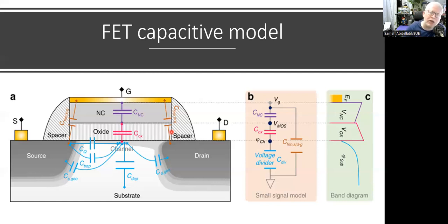So, generally speaking, we know that a capacitor is a junction or a formation of an insulating layer between two conducting layers. However, this is the ideal shape, because when we study the p-n junction, we know that in a p-n junction, we have a capacitor. We don't have an insulator, we don't have a conductor, but we have a capacitor because we have a depletion region and two partially conducting, partially semiconducting regions. That's why we have a capacitance in the p-n junction, especially when it's in the reverse bias condition.